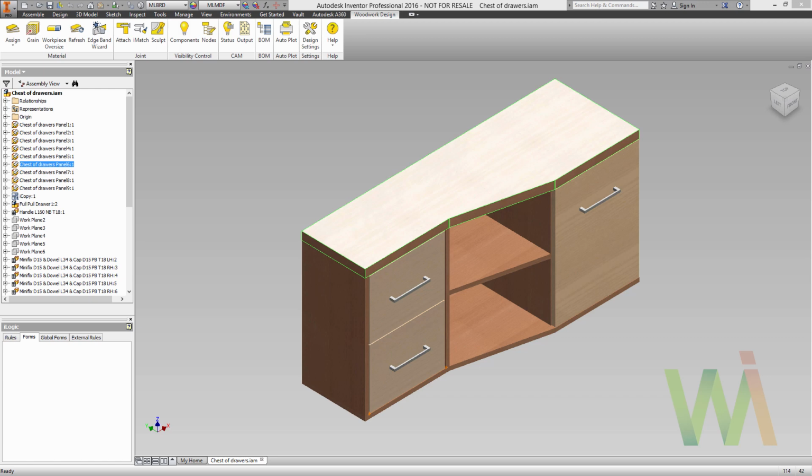This tutorial will teach you how to generate CNC programs based on an existing 3D model. As an initial model, you can use the results of your previous trainings, or you can use the model from a tutorial dataset. First of all, make sure that you have set a workpiece oversize in the right way. You can do this by going into workpiece oversize.